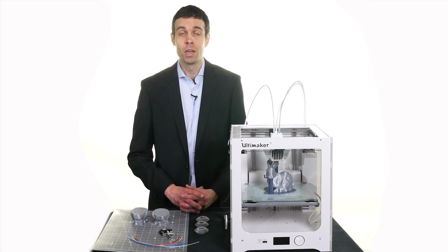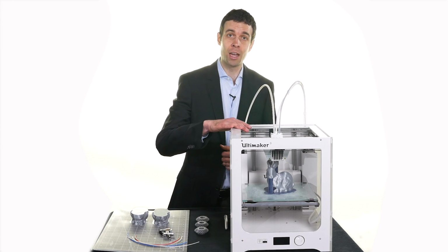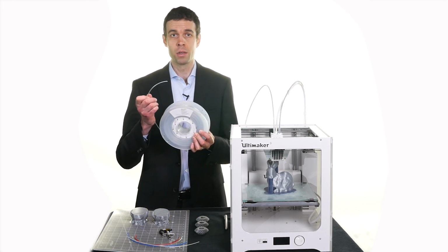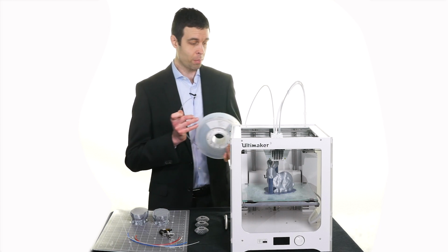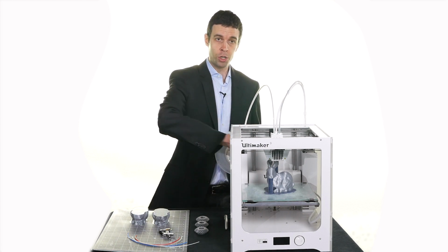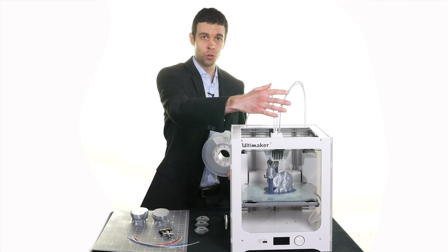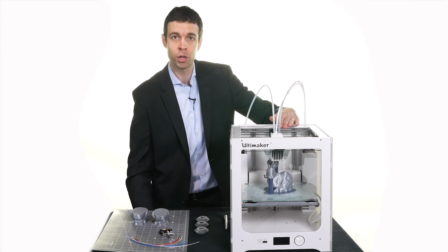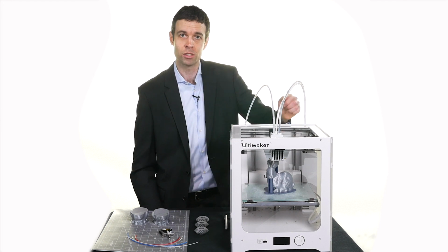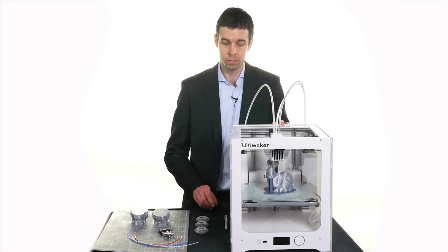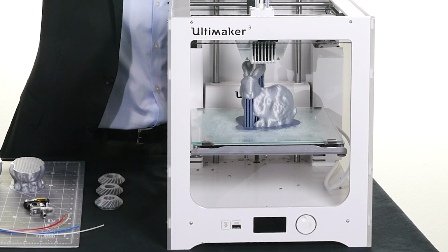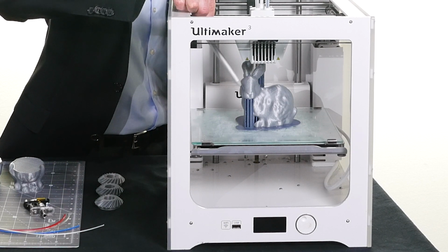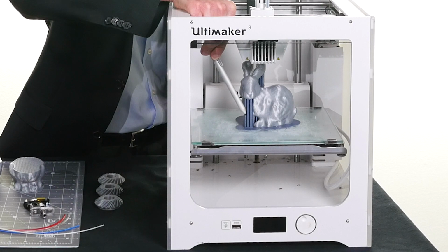For each AM process we study, I'll say we want to follow the material from raw feedstock to finished part. So for extrusion AM, using a desktop 3D printer like this, the feedstock is typically a thermoplastic filament, which comes in a spool and mounts to the back of the printer. Now in this printer, the filament is conveyed through these guide tubes to the printhead, which translates in X and Y in the planar orientation relative to the stage, which translates down in Z as the part is built. And we recently printed this bunny model, just like the bunny you saw in last week's introduction, where this is of course the part, and the second color represents the support structure.